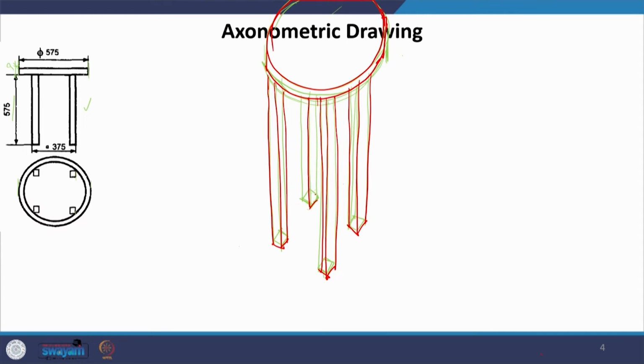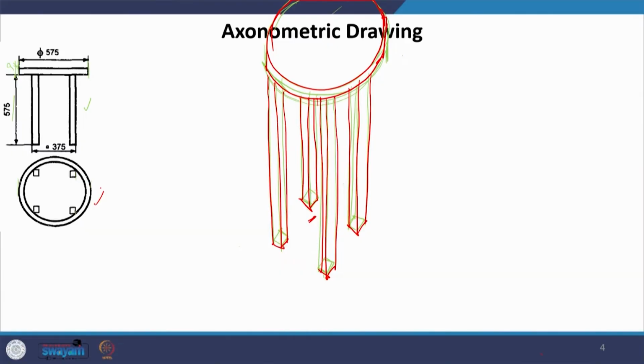So, I will anyways draw it, but when you will draw it, you will realize that this will not be seen. This is simply how we will draw axonometric, and it actually gives a very clear, fair idea of how this object looks like. We could have done it in isometric also, which was also correct, but then for that we would have had to measure the dimensions every time. Here all you can simply do is pick this, rotate it by 45 and extrude, just make the heights.